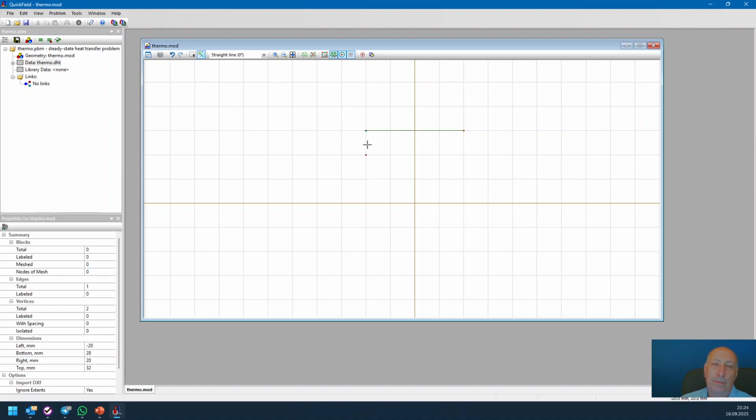How do I do that? I did it by dragging with the left mouse button pressed. Is it necessary to connect by an edge to existing vertices? Absolutely not. I can create an edge in free space. For example, simply drag from the starting point to the ending point, like this. And now I will create 2 vertical edges, this one and this one, and go back to the pointing mode